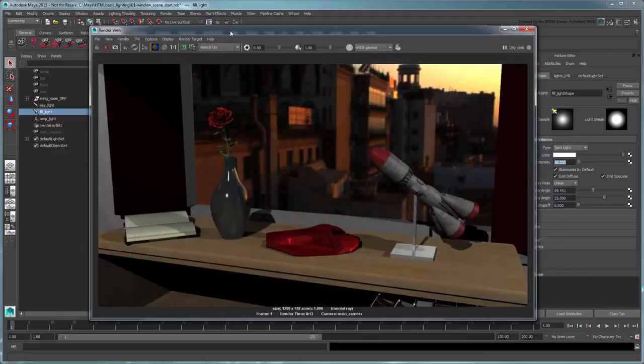Like those JPG and PNG files, scenes in Maya also need to be gamma corrected as well, since Maya assumes a linear luminance relationship. Part of the reason our render appears so dark is that this gamma correction is not being applied yet.